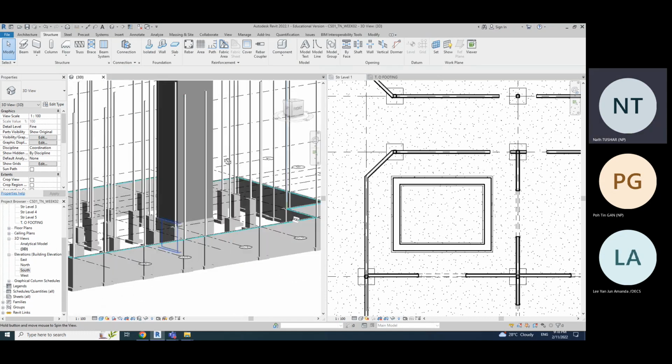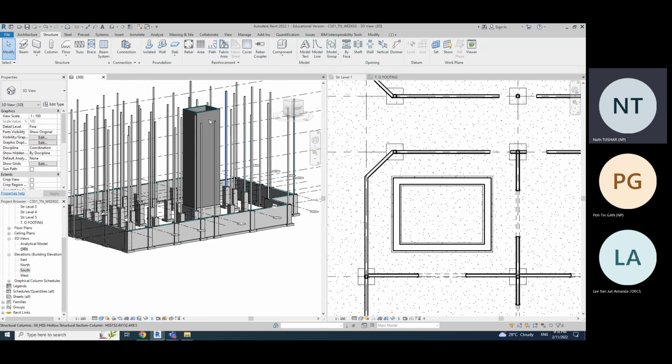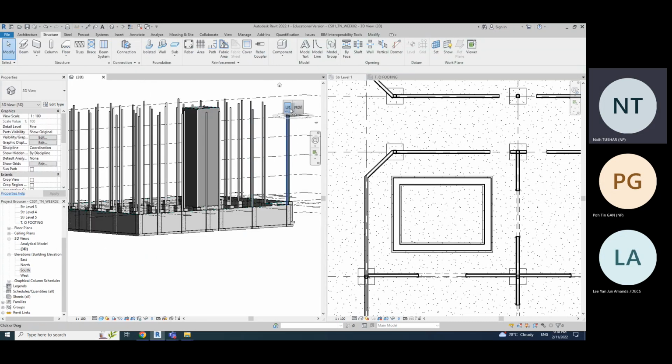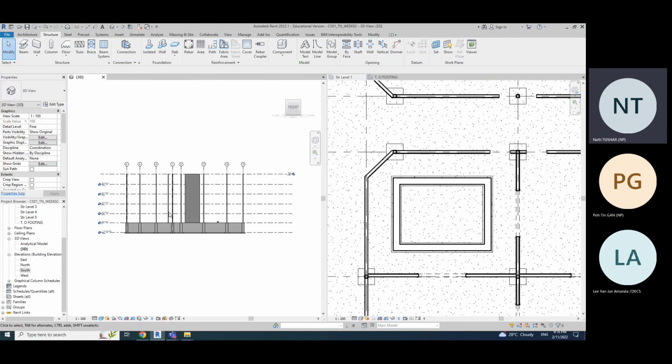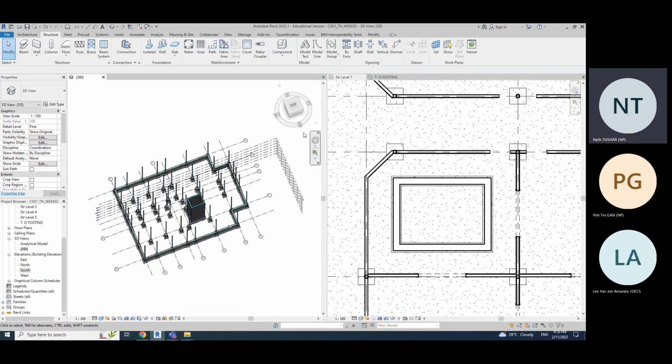When you draw your floors and all those things, it might automatically interfere and go inside this shaft, so it will block the pathway. So to do that, we are going to create from the very beginning an opening all the way that goes inside the shaft. So under the structure tab, go all the way in the opening, find this command called shaft.